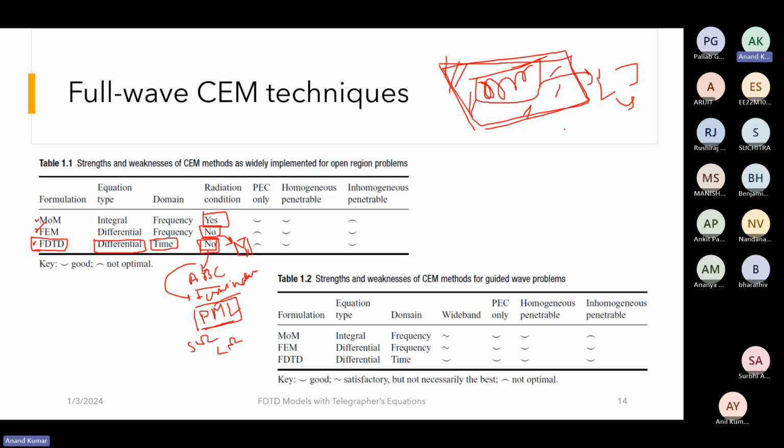If you have used HFSS, you will remember that when you design an antenna, you include a radiation box around the structure which you're simulating. If you have an object here, you give some gap around it so that you get your correct results. Similarly, in FDTD, if we are simulating a particular region, for example, if this is 1D, we have to make sure we terminate the boundaries correctly. Otherwise, when the wave reaches here, it will reflect back into the space.